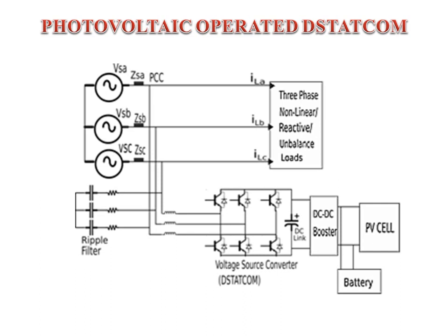So this voltage source inverter can convert DC voltage stored in the energy storage device, that is the DC link, to the output voltage AC in three phases. The generated voltages are in phase with each other by using a coupling transformer and are connected to the grid. By altering the phase and magnitude at the output of the shunt compensator, we may regulate the flow of active and reactive power between the shunt compensator and the grid.